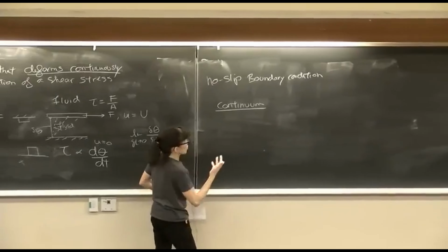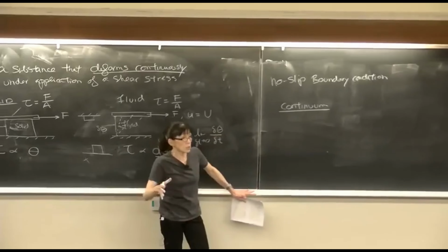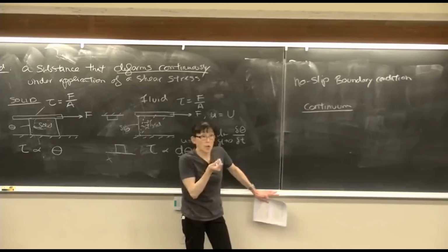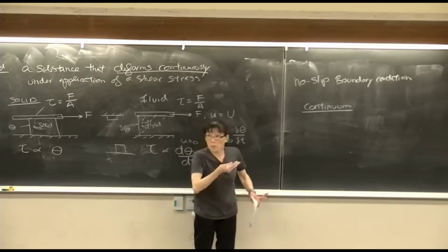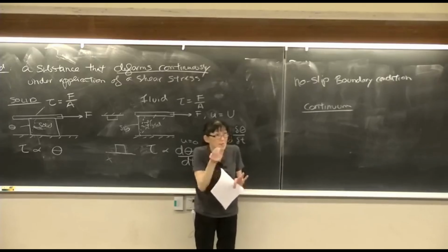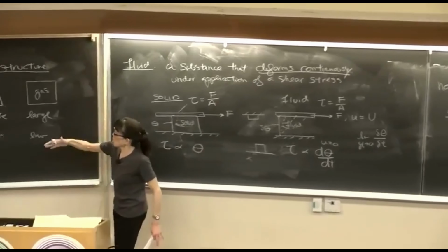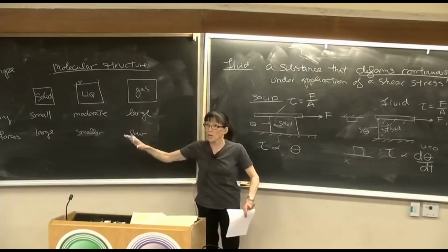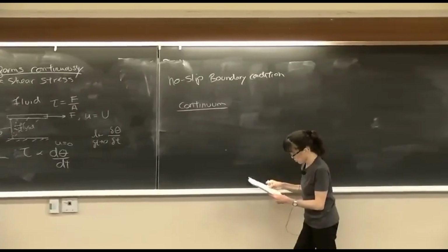So in general, we're going to always assume that the fluid is continuous and consider a macroscopic perspective versus considering the motion and behavior of all the molecules. But ultimately, or physically, in reality, what the fluid does is due to all of the molecules that are within the fluid. So from time to time, we may go back to a molecular point of view to understand why the fluid behaves that way, but in all our analysis, we're going to assume a continuum.